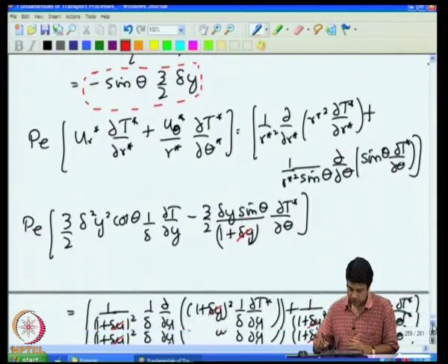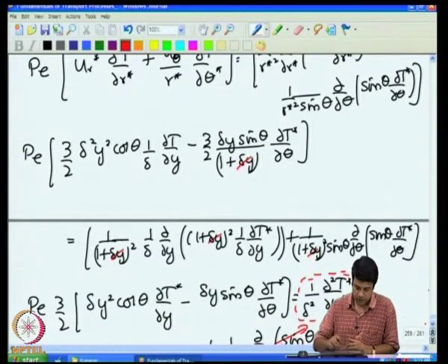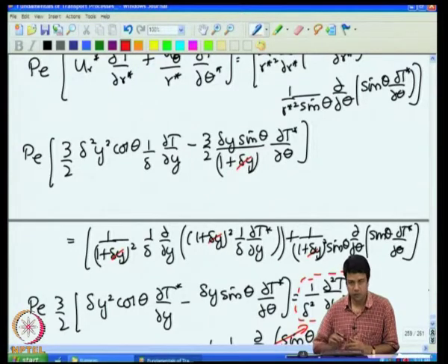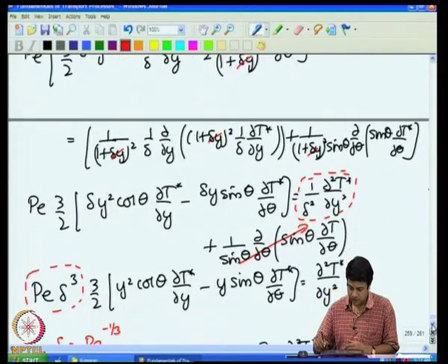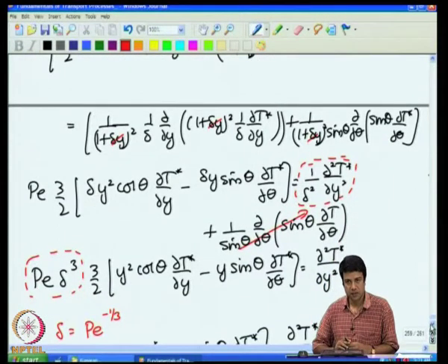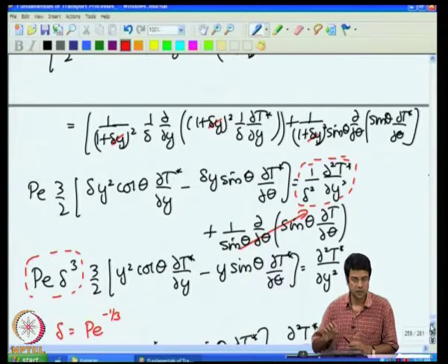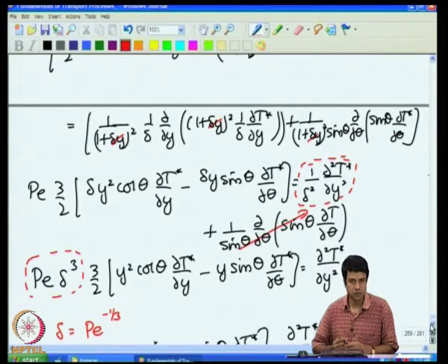This was inserted into the conservation equation and we did an expansion in delta y. Wherever we had 1 plus delta y, we neglected delta y in comparison to 1. In this case as well, we found that the cross stream diffusion is large compared to the streamwise diffusion. Here r is the cross stream direction and theta is the direction tangential to the surface. As the boundary layer thickness, which is proportional to delta, becomes small, the cross stream diffusion term goes as 1 over delta square, whereas the length scale in the streamwise direction is still capital R. So the streamwise diffusion remains the same, and as delta goes to 0, the cross stream diffusion becomes large compared to the streamwise diffusion.